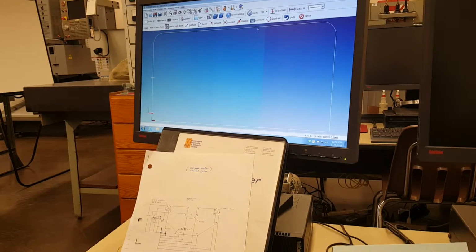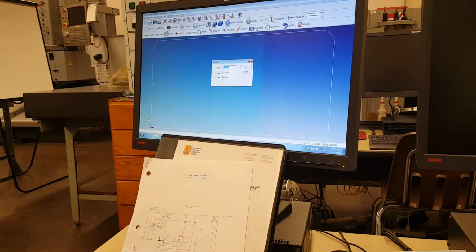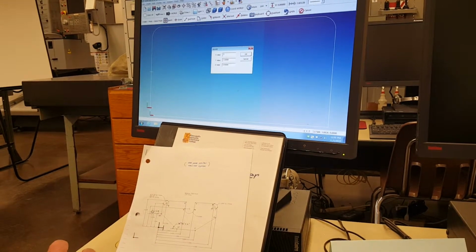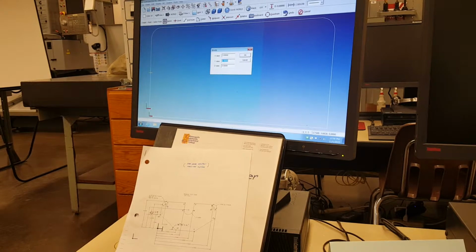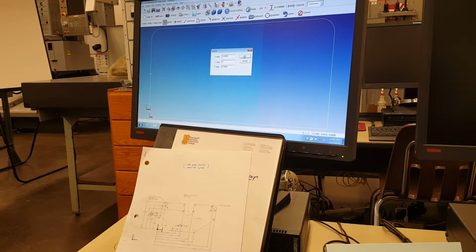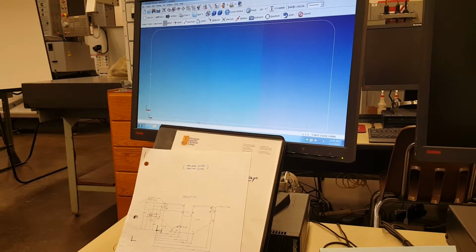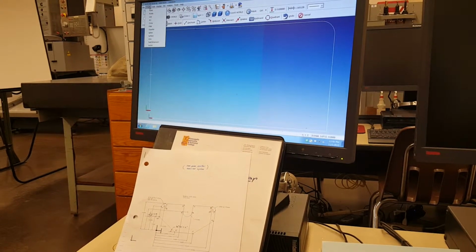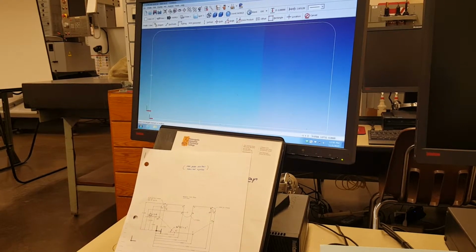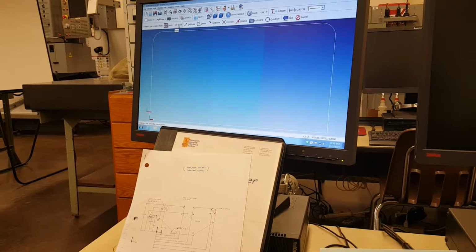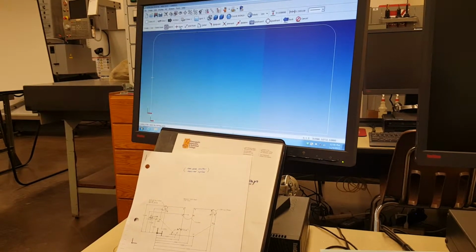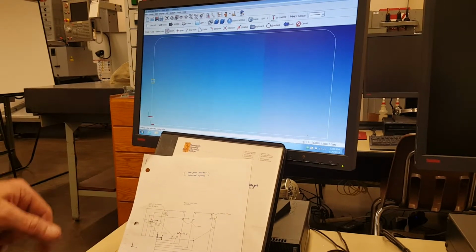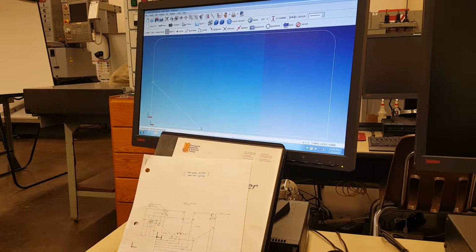Now I'm going to go keyboard again, now it's going to be x2, tab down, and 0. And hit OK. So now I've got my 2 points, and when I want to create a line, create a line, endpoints, point. Creating a line, select the starting point right there, ending point there.